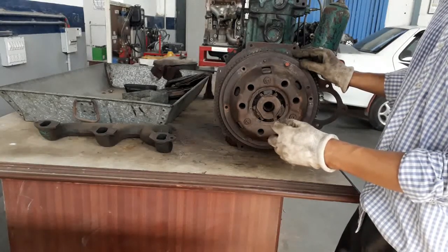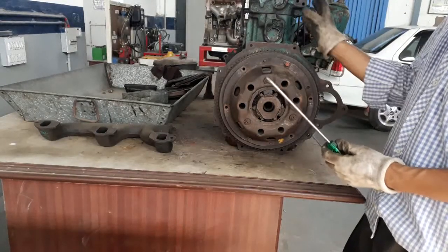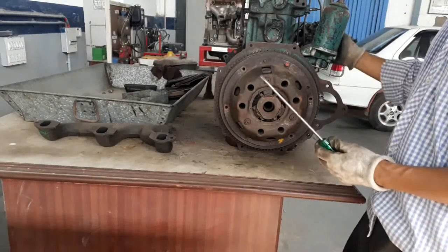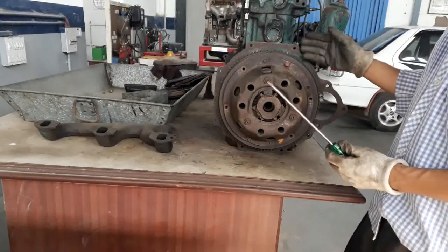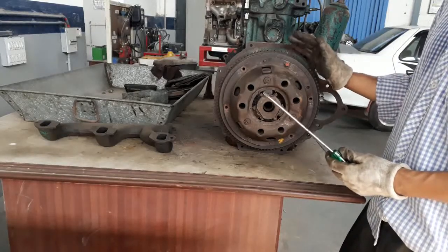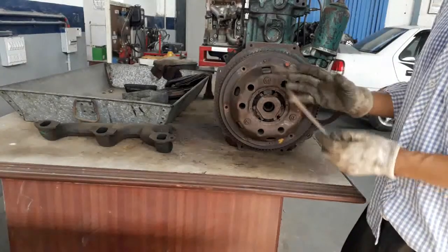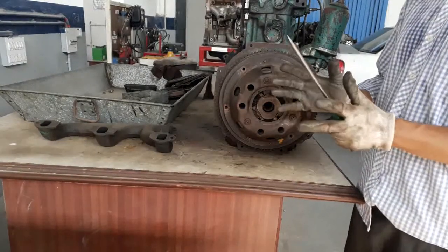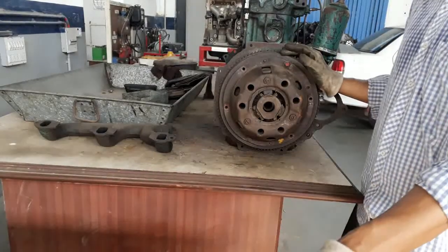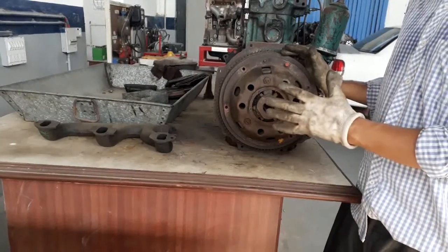The power is produced in the combustion chamber and transferred to the crankshaft, and ultimately goes to the flywheel, and from the flywheel the power is transferred to the transmission system. But between the flywheel and the gearbox there is a clutch unit. These units engage and disengage for the power cutoff system.